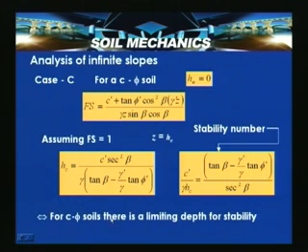So, for c-phi soils there is a limiting depth for stability. That should be noted. Previously, in the case of a frictional soil, the factor of safety expression is independent of the depth, but in this case, for a c-phi soil, there is a limiting depth for stability.